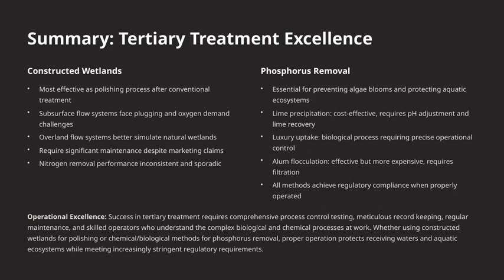Let's wrap up with a summary of tertiary treatment excellence. First, when it comes to constructed wetlands, they are most effective as a polishing process after conventional treatment. However, subsurface flow systems often face issues like plugging and high oxygen demand, which can limit their effectiveness.